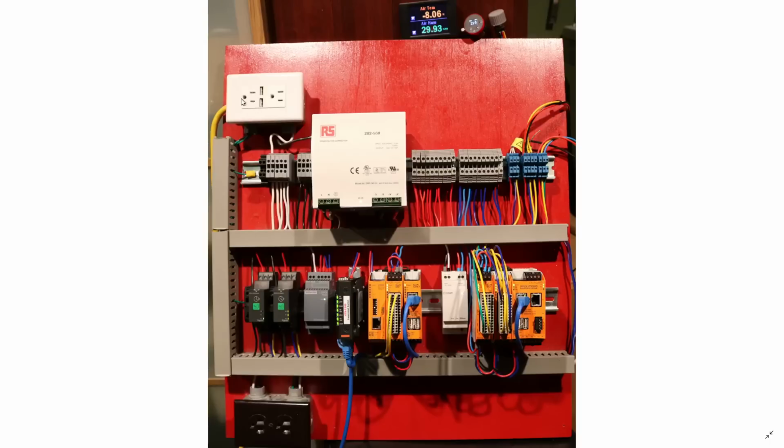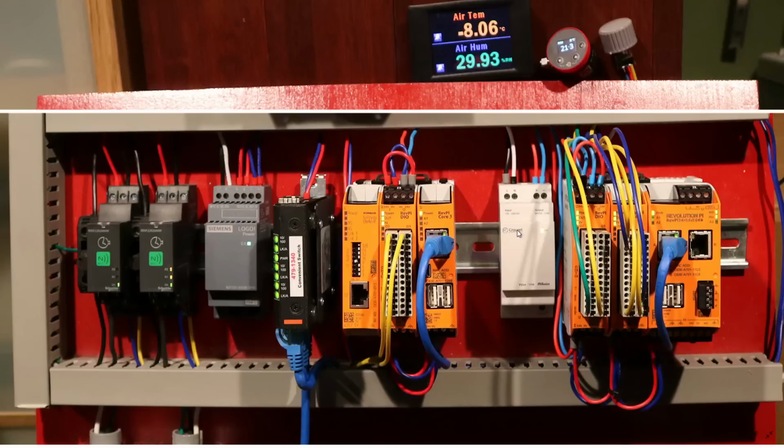What we have is our mains coming in, just a little utility socket up here. We have a 24 volt 10 amp power supply for driving I/O devices. Don't have much connected to that right now as far as a load is concerned. Okay, so the Revolution Pi Connect has got an AIO module and a DIO module connected to it, same as we had set up in the previous videos, and two of the analog outputs are being sent up to the Lascar dual display module, and that takes in two analog inputs.